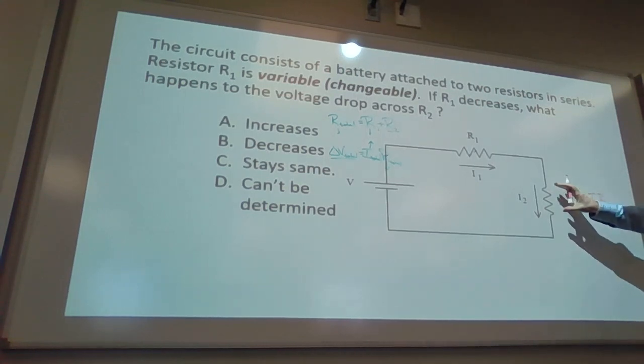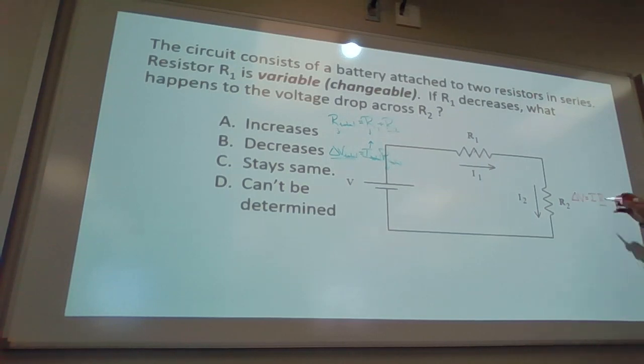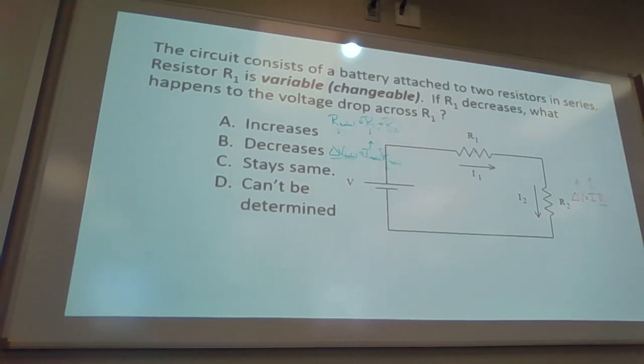Okay, what stays the same here for this scenario? Which measurement stays the same for this guy? We did not change the resistor. Okay, we found that the total current goes up because it's series, so everything goes up, same throughout. Therefore, the voltage does what? Also increases. See how we walked through that one? Okay. Same scenario, but what happens to the voltage drop across R1 now?